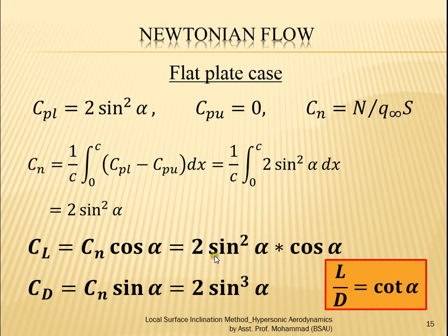Numerically both are the same, but when we take CL or CP, we take the deflection angle and resolve it into sine and cos components. Here the deflection angle equals the angle of attack, so both are the same. So CL and CD given by these equations are valid only for Newtonian flow in the hypersonic regime, and the L by D ratio is always valid.